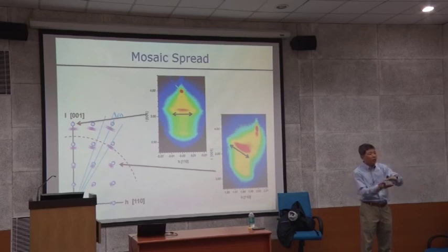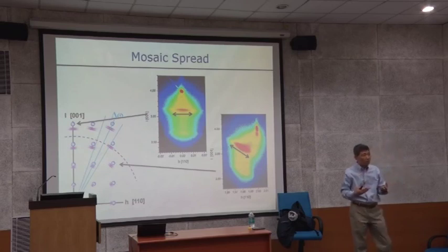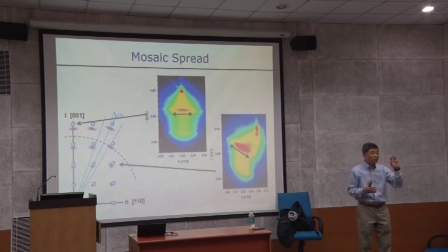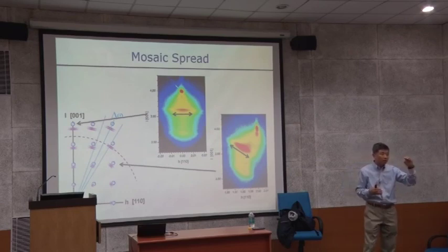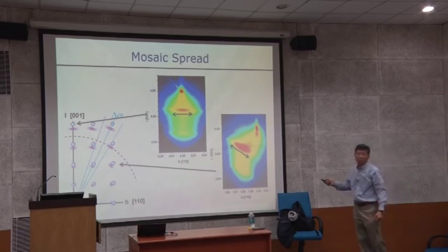So we have only one atomic layer, one unit cell, 10 unit cells, 100 unit cells, millions of unit cells. Your cancellation is not perfect. So when you get a smaller number, that's why you get peak broadening, which we call the Scherrer formula. I'll talk about the Scherrer formula later. That is peak broadening coming from size: your grain size, film thickness. The size effect is a peak broadening coming from here.